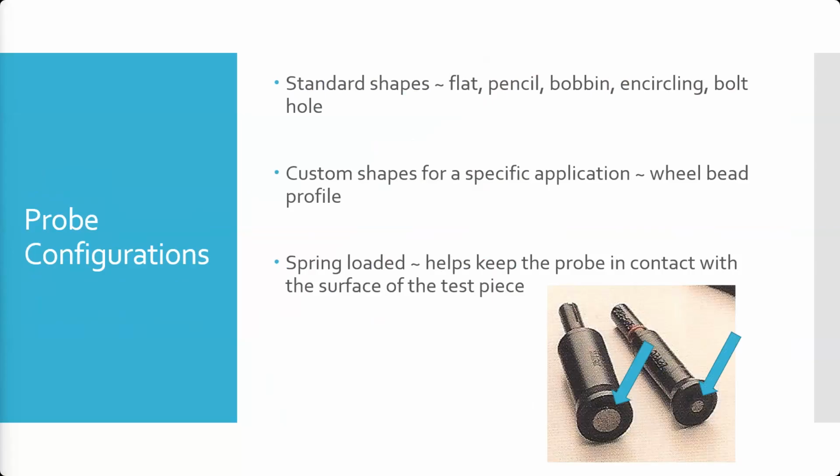So which one is our higher frequency probe, left or right? Right, high frequency has a smaller coil in it. Left probe is higher or lower frequency? Which one is going to typically be used for near surface, closer to the surface flaws? The right one is going to run a high frequency. It's going to have a lot higher resolution, but it's going to be limited in depth of penetration.